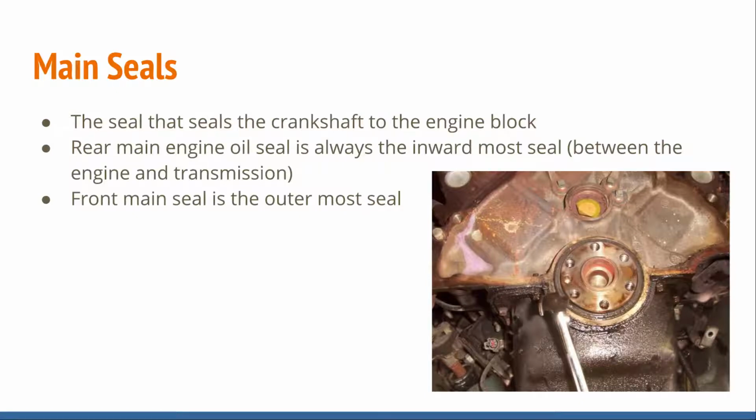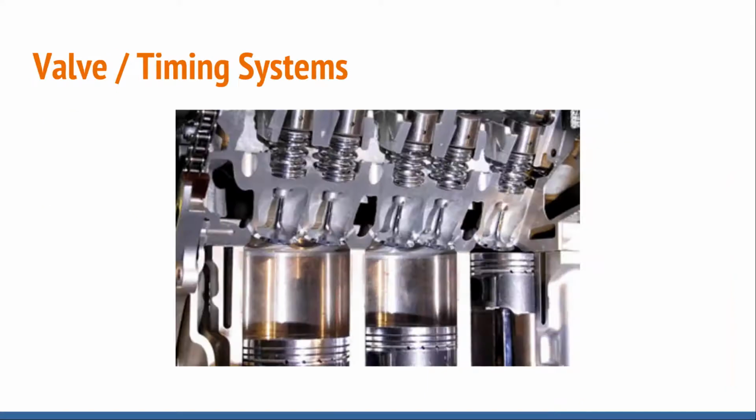Some guys probably replace them every time they take a transmission down. What I do, if I have the transmission down, I'll take a look at it. If it looks at all wet or if it's starting to seep, I recommend replacement of it. If it's bone dry, I usually leave it alone. So it's whatever you get in the habit of doing, whatever you're used to.